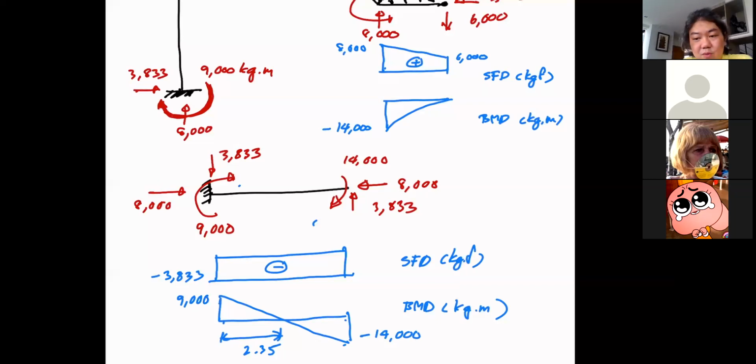You know, one more thing, if you don't have a question, at this piece, you have two values for moment, the positive and the negative. But this is a positive moment, so it should bend like a positive moment, right? Like this. Don't forget that we begin with 0, it bends like this, and then that's a point of inflection where it bends back. See that?